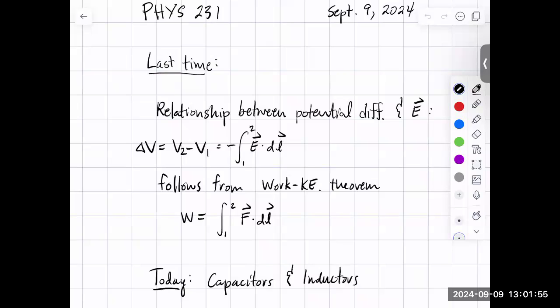That makes intuitive sense, because the charges have to flow through this resistor, which is opposing their motion, so it's taking energy away from these moving charges. You're losing potential energy, or a related concept, voltage, as you go across. So when you cross a resistor in the direction of the current, you lose voltage: the voltage difference is minus I times R. On the other hand, if you cross that resistor anti-parallel to the current, you gain voltage of plus I times R.